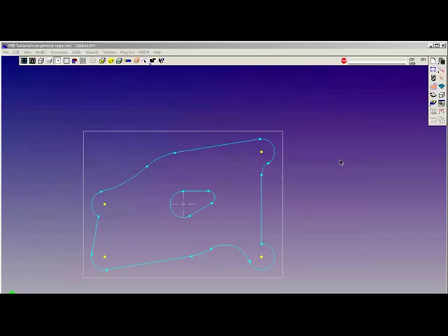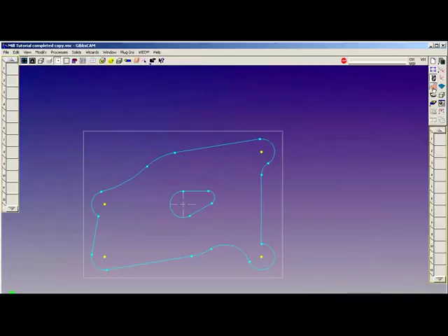the geometry creation aspect. We simply brought in a part that has already been drawn, and we're going to apply the toolpath to it. What I'd like for you to do is just observe as I walk through the dialogues and tiles and apply the toolpath to the geometry. First of all, I activate the tool list and the cam list.